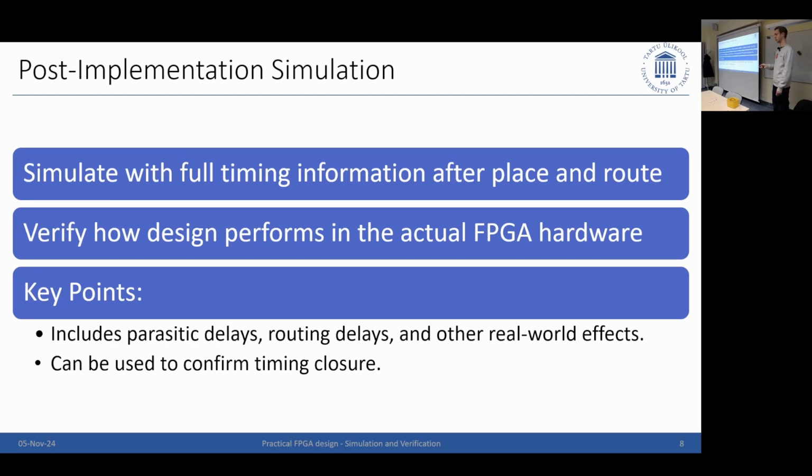If you cannot show that your design works here, but it works on a chip, then you run into the risk that the next batch of boards will just not work because of the manufacturing differences. So maybe you coincidentally have a very good quality FPGA, then it's good.